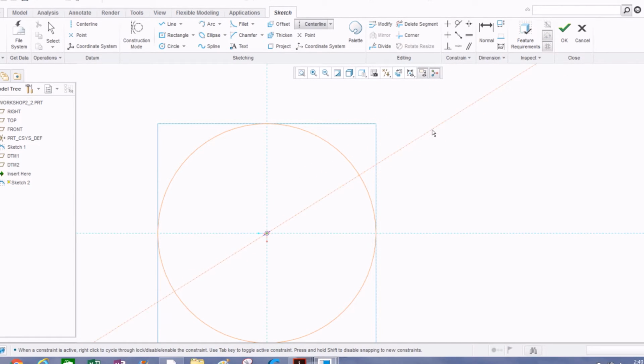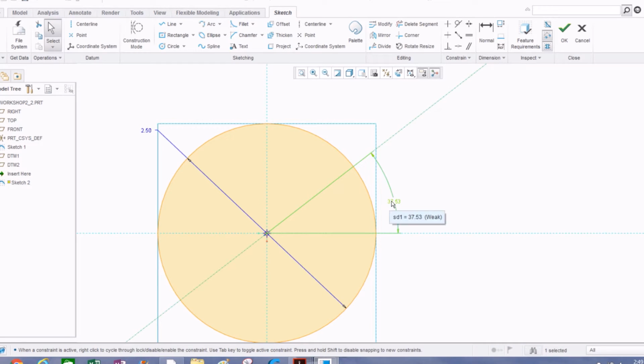Alright, well there's two ways of doing this. I thought that would work, but we can actually just click anywhere, create that center line, and we get prompted to change an angle here. So I just clicked anywhere to place it and changed that to 45. You know, that works on the one at work. I guess must be something different here. But we're accomplishing the same operation by changing it to 45 degrees.